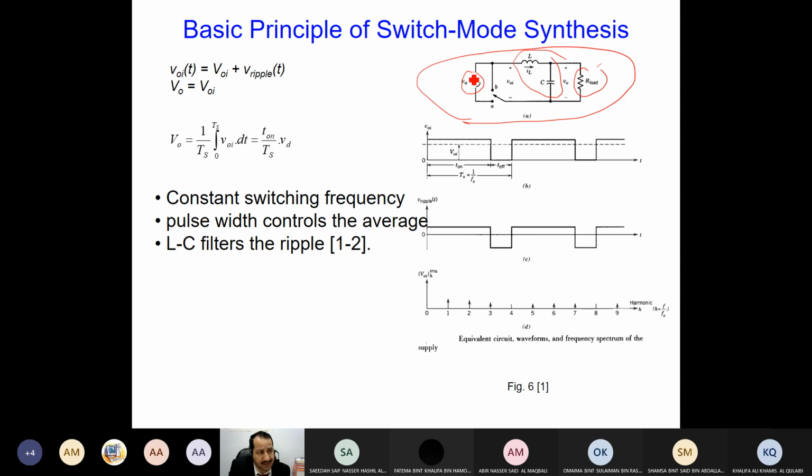Now here we have a DC supply. In the previous slide, the transistor and diode and the transformer with the 3 windings work this way, like a switch. Either it is on A, so the circuit is closed, and the current will flow here, and we have a closed circuit. Or it will be on B, the supply will no longer be available, and we have only the inductance in parallel with the capacitor and the load.